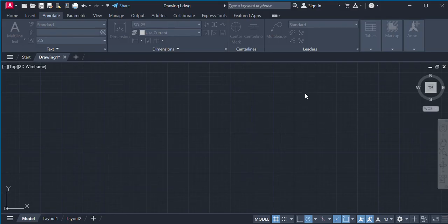Then select regular. Then when it gets to the size, please tick on annotative. Annotative objects and styles are used to control the size and scale at which annotation objects are displayed in model space or layout. Please make sure this is ticked. Then on the paper text height, you can specify 3.5.